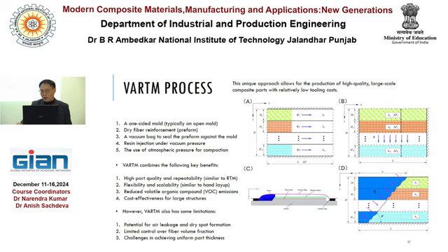This is the resin outlet here, and the vacuum pump is needed to make the vacuum condition inside the vacuum bag. Outside the vacuum bag, there is only the atmospheric pressure. So atmospheric pressure will compact the composite material structure. So the molten resin should propagate and infiltrate in this kind of shape.